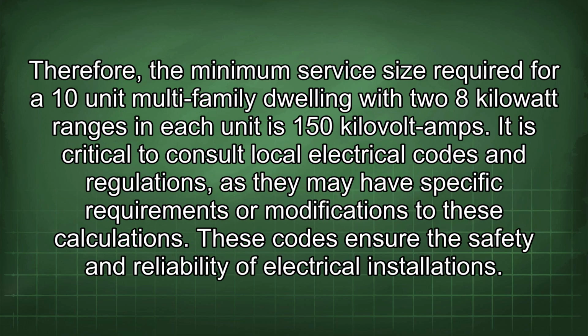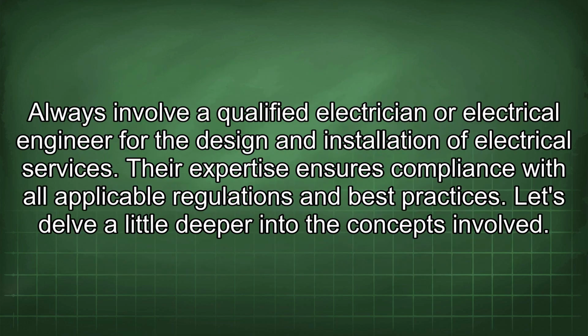Therefore, the minimum service size required for a 10-unit multi-family dwelling with two 8 kilowatt ranges in each unit is 150 kilovolt amps. It is critical to consult local electrical codes and regulations, as they may have specific requirements or modifications to these calculations. These codes ensure the safety and reliability of electrical installations. Always involve a qualified electrician or electrical engineer for the design and installation of electrical services. Their expertise ensures compliance with all applicable regulations and best practices.